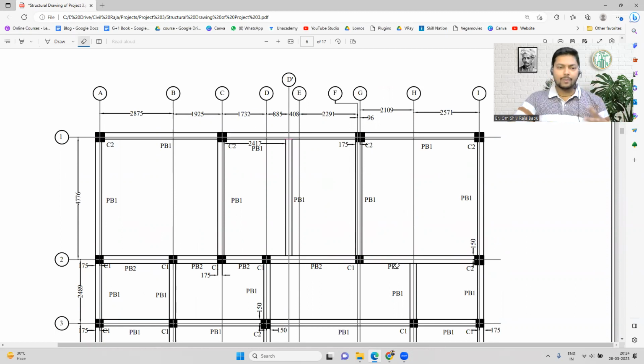Okay, so whenever we have to provide the details, we do not simply copy it from STAAD Pro or Tekla Structural Designer. We just categorize every beam into such an axis. Okay, so suppose if you are using the RCDC software, then it will automatically arrange it according to the axis. But normally when we are working on STAAD Pro, I haven't used ETABS much, so I don't remember that much. But in STAAD Pro and Tekla Structural Designer, these two softwares, we will not find any categorization of the axis. So we have to categorize it. Okay, so that can be done manually.